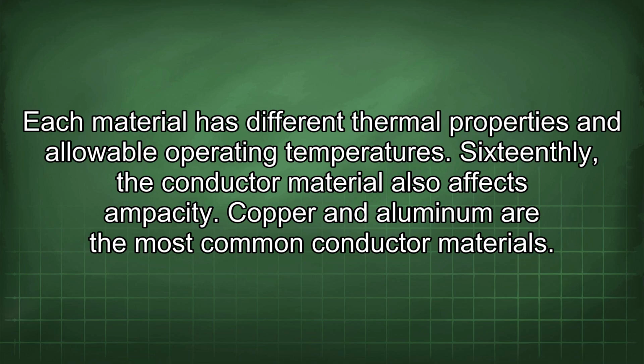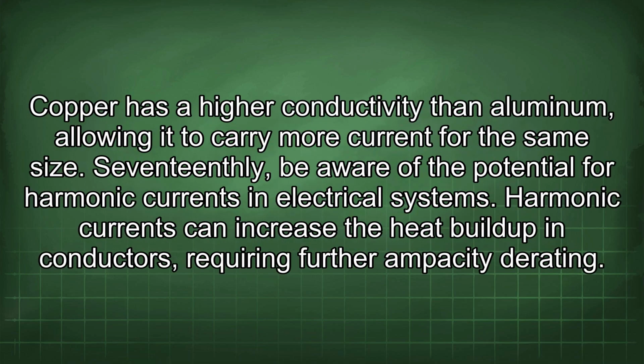16thly, the conductor material also affects ampacity. Copper and aluminum are the most common conductor materials. Copper has a higher conductivity than aluminum, allowing it to carry more current for the same size. 17thly, be aware of the potential for harmonic currents in electrical systems.